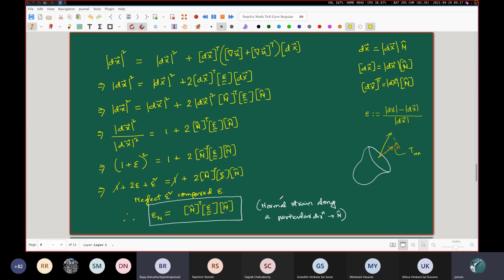So let me tell you this. I will release the tutorial sheet today. You will see the values of the strains that we are working with. Most of the values will be in the order of 10 to the power minus 6, or 10 to the power minus 4 actually, because it is something like 350 times 10 to the power minus 6. So the order of those answers for the strains is usually 10 to the power minus 4. And that is not something which is just a product of a textbook answer. In real practice also, these are the kinds of values which get measured.